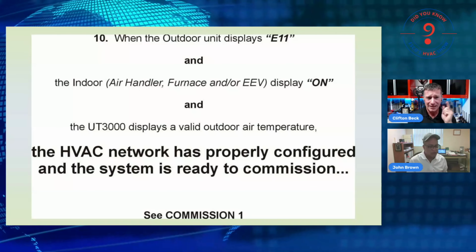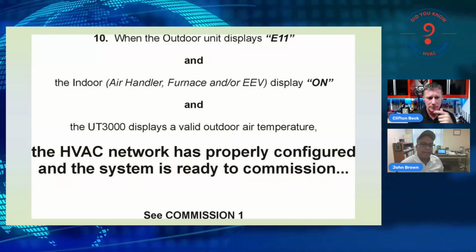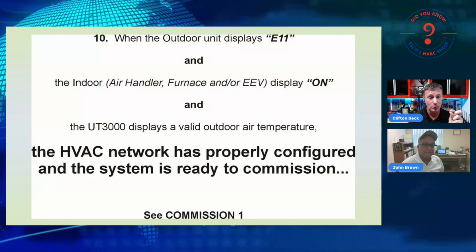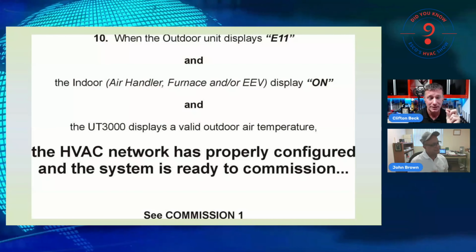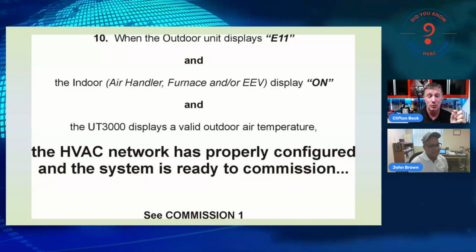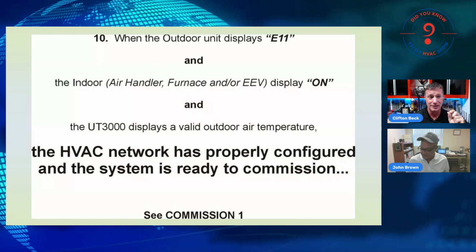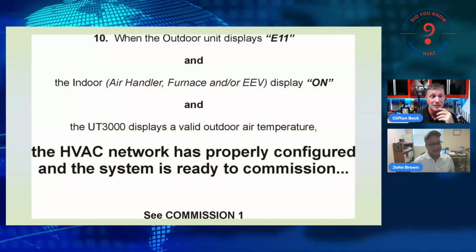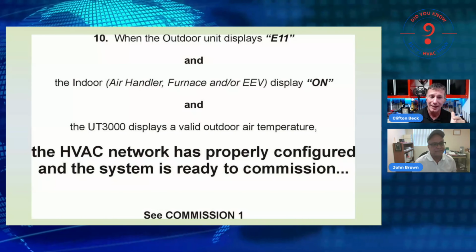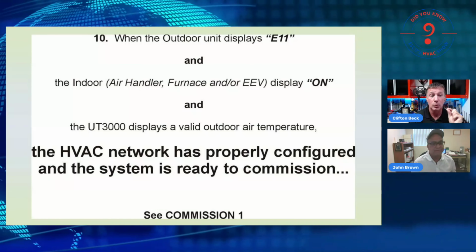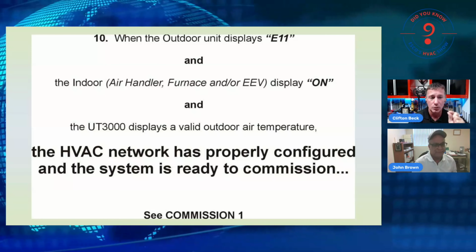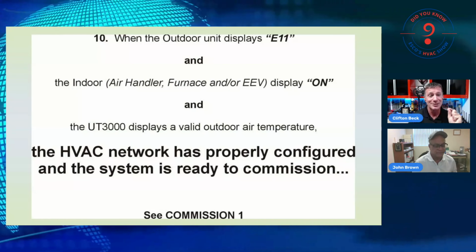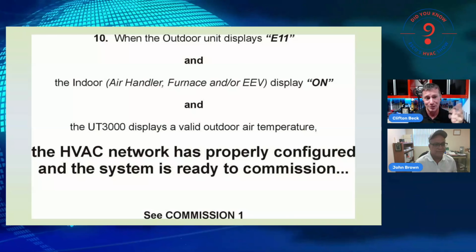A lot of you people know, ask about that. They'll say, do I have to add an outdoor air temperature sensor to this if they first get that code where they're not reading an outdoor air temperature sensor? And for those people who are familiar with the older Honeywell CTK series and the Honeywell communicating systems, the Prestige, where you can add outdoor sensors, a lot of people ask, well, do I need to add that? No, we are utilizing the outdoor temperature sensor of the outdoor unit, one of the many sensors and thermistors that we have on our new inverter technologies.